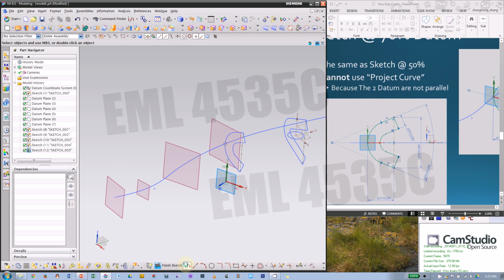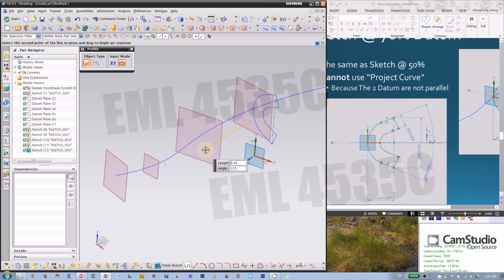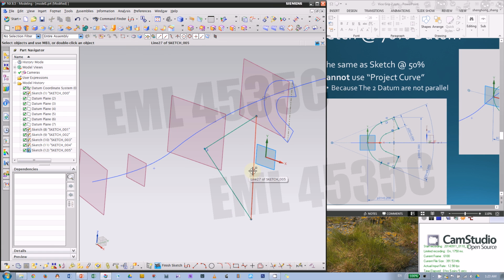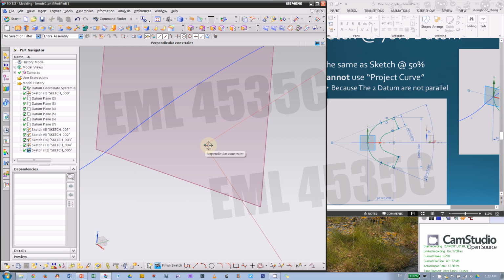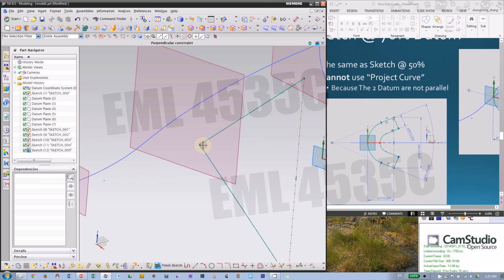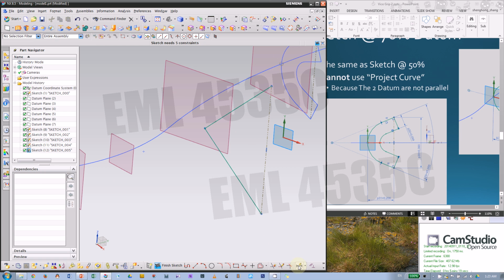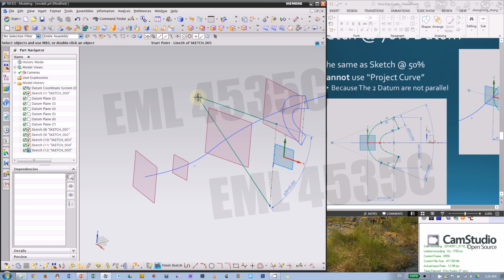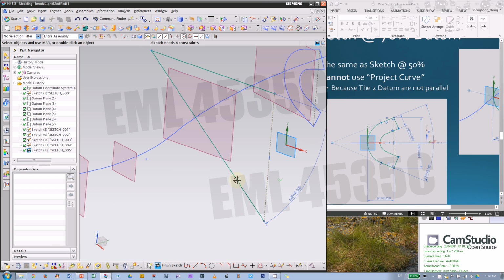slides. First, the profile tool, triangle. Now, in this case, my supposed-to-be vertical line is not vertical, so I just click this line, turn this to vertical, and click again to turn this to reference. And that should not be a perpendicular constraint. It's automatically added. So delete that, and give this an angle of 45 degrees. And you can try to drag it. If it's not working well, just back up.